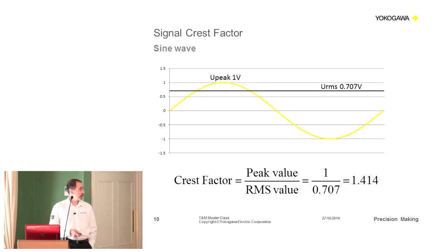On a standard sine wave, non-distorted, my Crest factor is 1.414. Well, it's not quite, it's actually √2, but 1.414, almost exactly. And basically it means that when I have very high Crest factors, my measuring instrument has to be able to handle those high Crest factors.